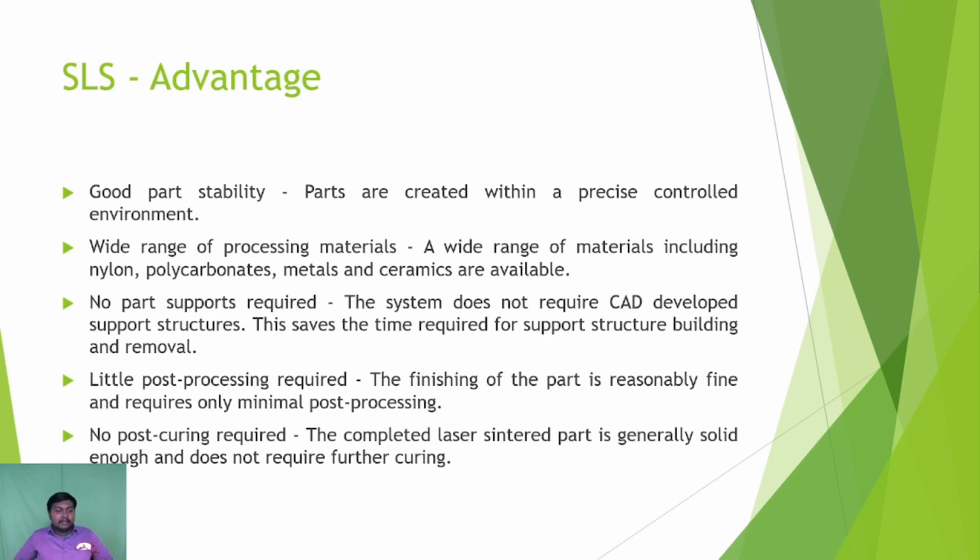The fourth one is little post processing required. Post processing is very minimal. Finishing of the part is reasonably fine and requires only minimal post processing, and no post curing is required in the selective laser sintering methodology.